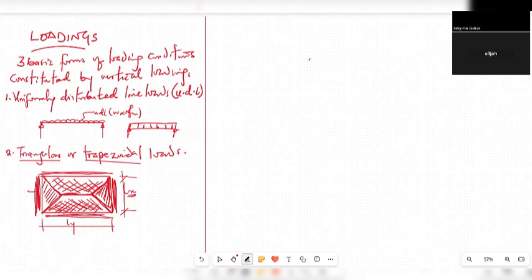When you finish drawing out your yield lines, you discover that you have two basic shapes: the triangle and the trapezoidal shape. The amount of load that will go to this side of the slab will be proportional to the area of that triangle at that point.